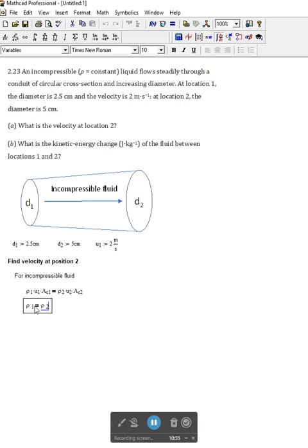And so again, I say row 1 is equal to row 2. And let me just retype that for you to show how we get Greek letters. To get a Greek letter, and I prefer to use Greek letters where I can, rho is the lowercase r in our English alphabet, so R. And then to get a Greek letter in MathCad, we type Control G. So R, and then you immediately hit Control G. That gives you the letter rho. And then dot 1, so it gives me my subscript 1.